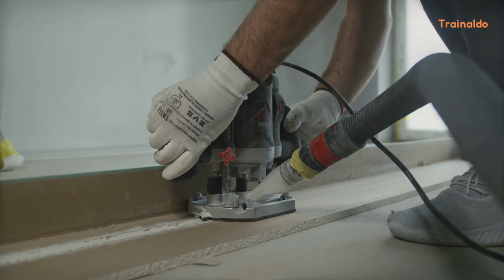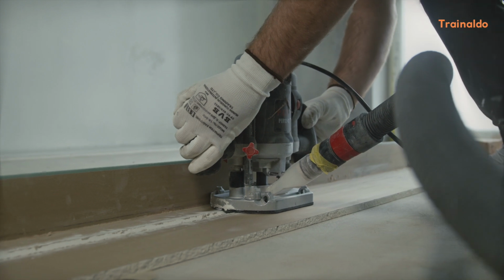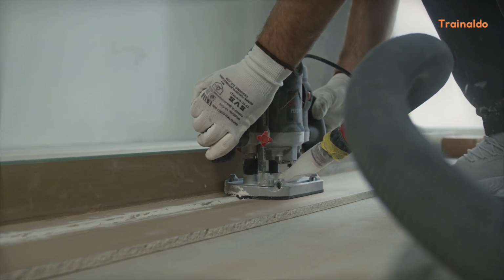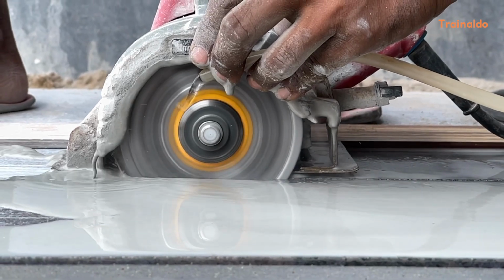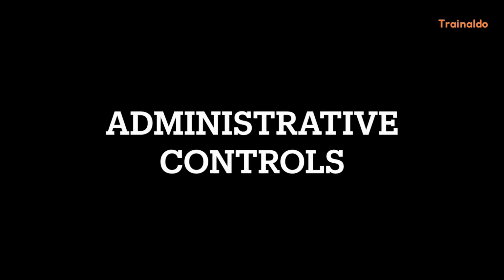Engineering controls. Next, we apply engineering controls to isolate workers from hazards. For example, if a construction task involves cutting concrete, install dust extraction systems or use wet cutting techniques to reduce airborne silica dust.